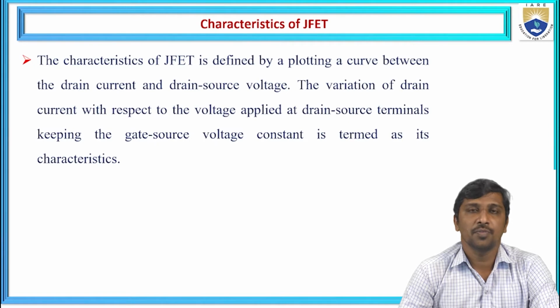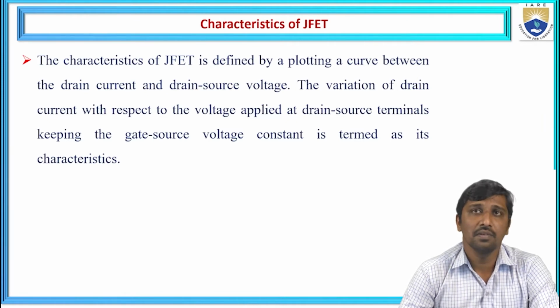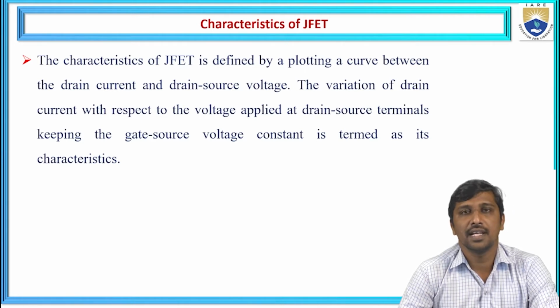If you want to plot the characteristics or identify the behavior of the junction field effect transistor, we need to apply a biasing voltage between the drain and the source, as well as a biasing voltage between the gate and the source.